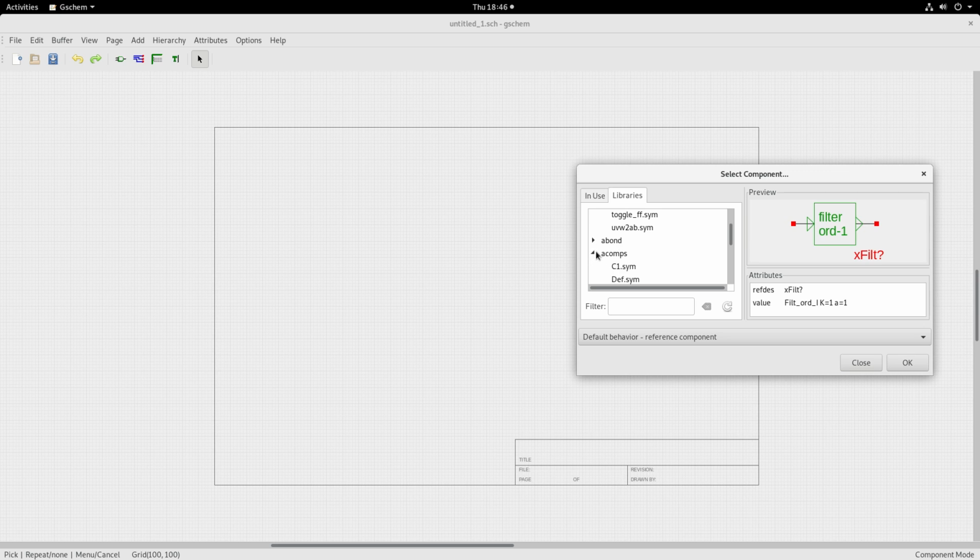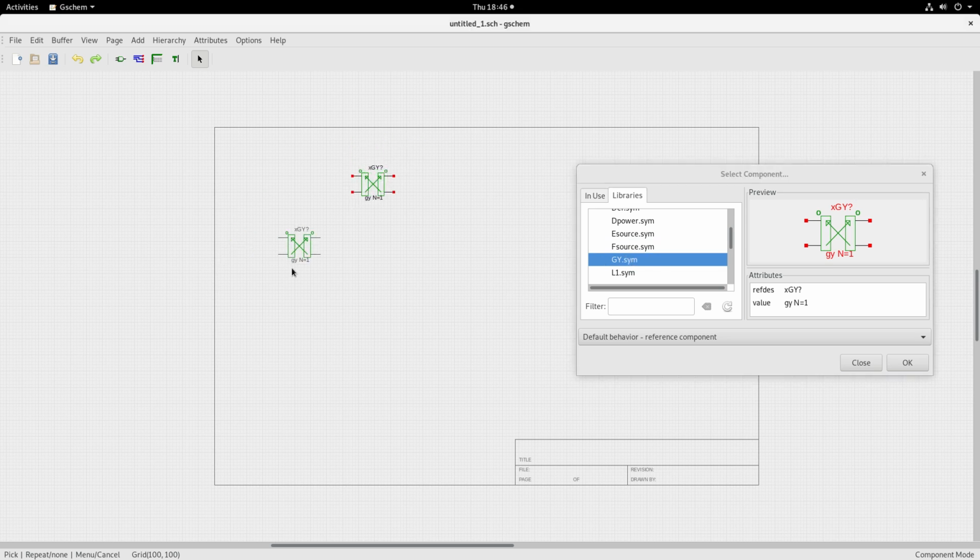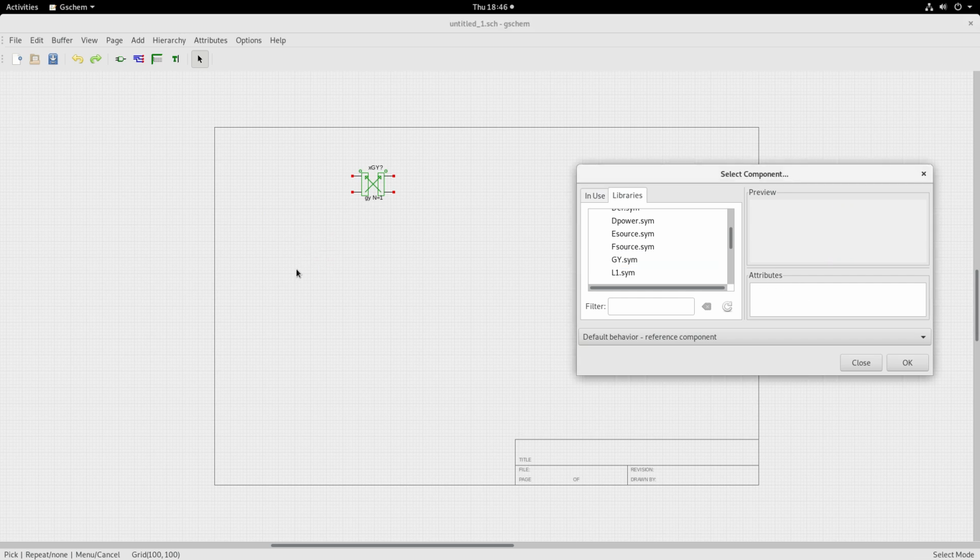And likewise for the components, there are various generic components which I have here, and a gyrator. So like that you can pull them and then place it like any other circuit component and use it to build your circuit. Of course we will use this later, but just now wanted to tell you that you can download this resource and it is free for you to use. You include it into the symbols folder in the GAF directory and you are ready to go while you are selecting the components.